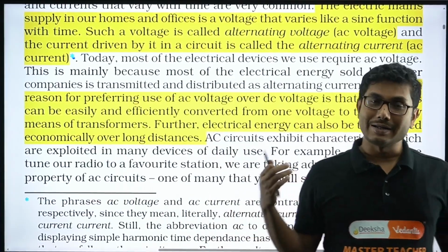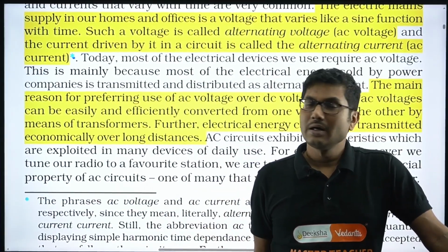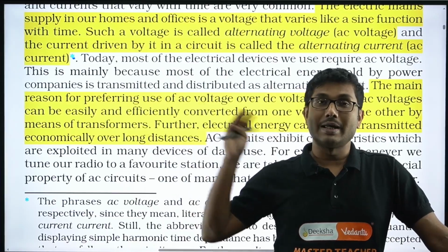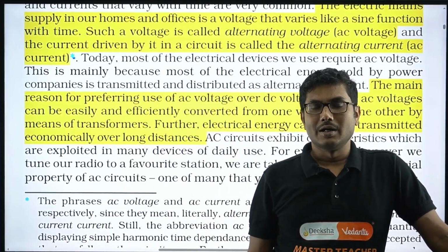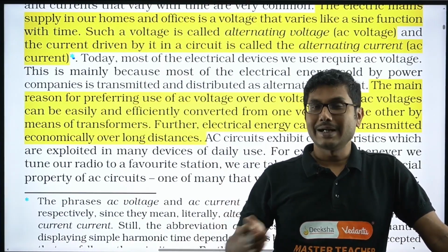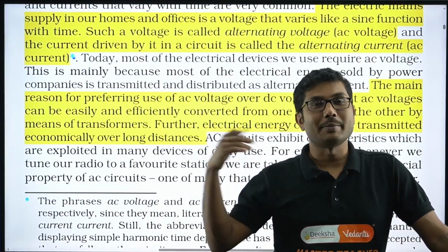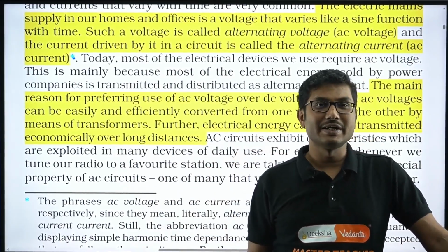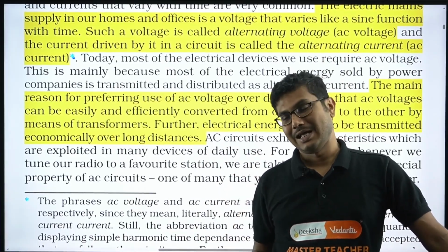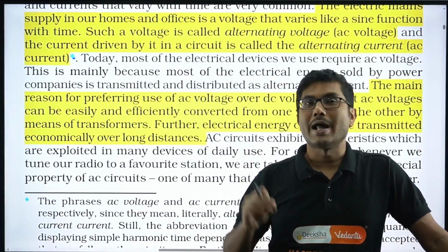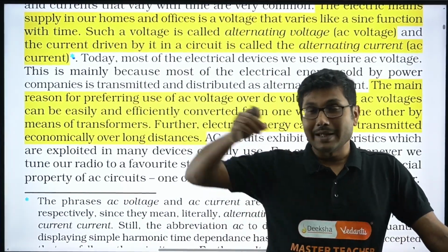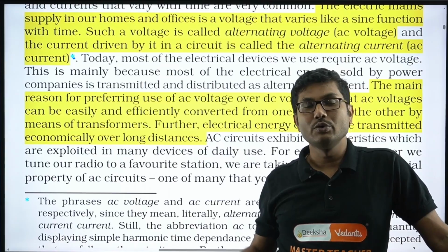Now R you cannot decrease beyond a certain level, right? Even if you use platinum wires or silver wires, you cannot decrease the resistance beyond a certain limit. Everything has a resistivity, we have already learned that. But if we change the formula to V square by R, and increase the R instead of decreasing it and keep the voltage higher, then the power consumed in the circuit will be much less. So that is how we keep the current low and voltage high to reduce the power loss in the supplying wires through which the current reaches your house to a minimum.